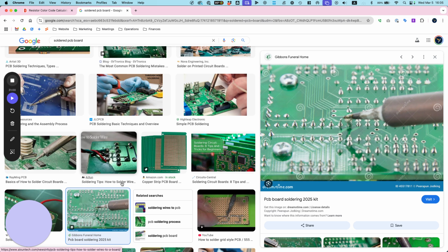So there's a couple ways you could do it. You could either try to pool a bunch of solder, but it's going to flow around, so it's a little difficult. You can also introduce another wire to jump from one to the next. Or what I'm going to do here is use this end piece as a wire. I'm going to bridge it across. So first I'm going to snip this one, all right? You see this one? Do you have the snippers?